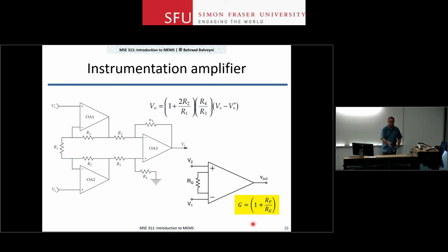Very easy to use, but as I said, at the end of the story, you get this circuit. So if you don't have an instrumentation amplifier, you can go and make one using 3 op amps as shown to the left. So that's that for the discussion on linear circuits, for measuring voltage, current, resistance, and capacitance.